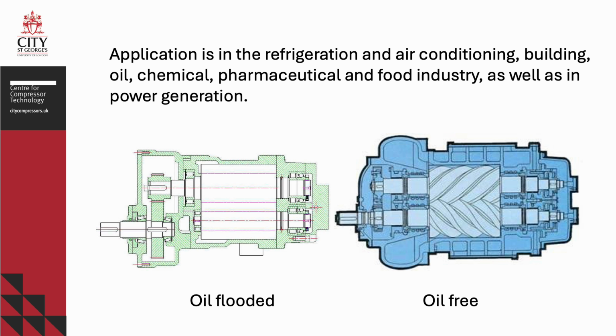When the oil is injected between the rotors, it serves to lubricate them and seal gaps between the rotors, as well as to cool the gas which is being compressed. However, as a result, the gas is contaminated by oil, which needs to be separated from it. This, regardless of the high level of separation, is not sufficient in the food and pharmaceutical industry, where oil-free compressors with synchronizing gears and rotor seals have to be used.